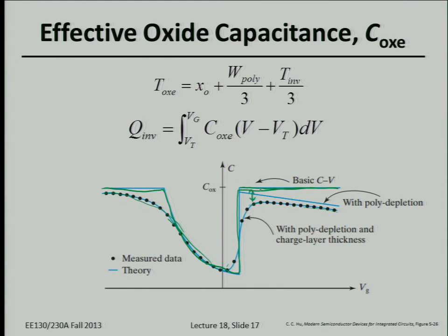And the reason this small signal capacitance degrades as you go more strongly into inversion is gate depletion. Remember, as you drop more and more voltage across the silicon, you'll get more and more voltage across the polysilicon gate as well. So the thickness of the depletion region in the gate increases. That effectively increases your oxide thickness and decreases your small signal capacitance.